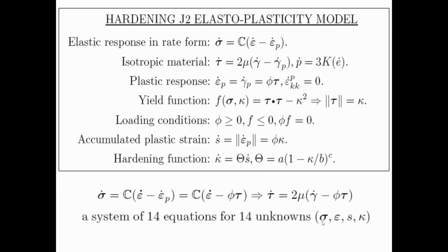That is 6 stress quantities, 6 strain quantities, one value of S and one value of kappa. I'm saying kappa here, it can also be phi, left to you. So if I have simultaneous equations of 14 equations and 14 unknowns, it is possible for me to find out all these quantities as the loading continues.